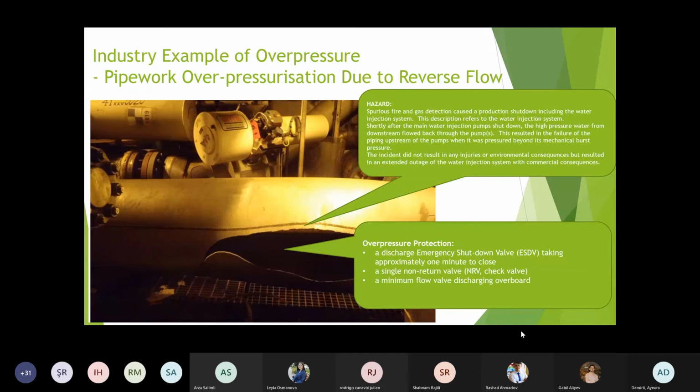In this piping, at the time of failure, some of the NRVs were known to leak. Even in this case, we skipped this risk on site. NRVs in water service frequently leak, and therefore can only be considered to reduce the amount of flow in the reverse direction, rather than provide a full barrier to reverse overpressure.